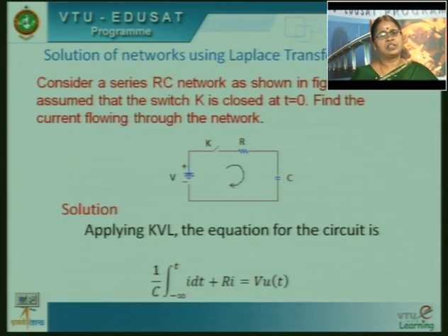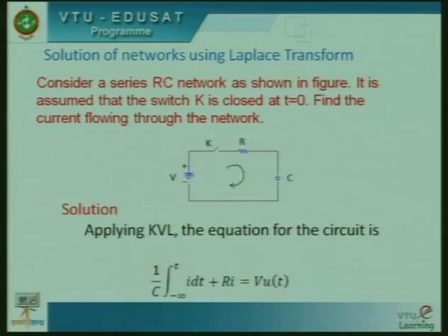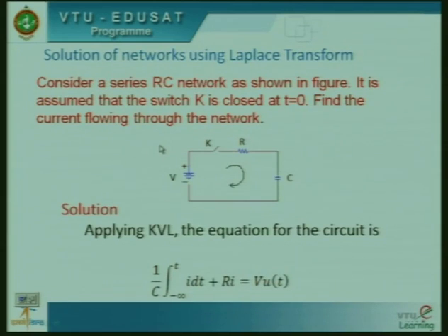So, we can convert the differential equation in time domain to an algebraic equation in frequency domain. And when we write the algebraic equation in frequency domain, that is by taking Laplace transform of the differential equation, we also incorporate all the initial conditions. So, we take care of even the initial conditions. Then once you write the Laplace transform, we manipulate the equations in S domain and try to get the Laplace inverse of the parameter which we are interested in. This is the procedure to be followed to solve the differential equations which describe the network.